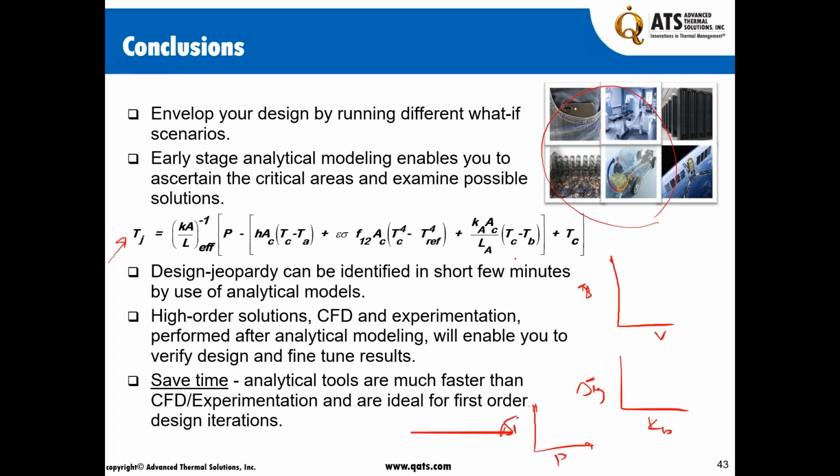It is so powerful to be able to go in there and say, okay, I can change these, and as long as you have a model and really envelope your design, you can say to your circuit designers, this board and this component with the power dissipations you've given me, you cannot put another board of the same power next to it. You've got to locate that in a different location of the system, because the coupling that takes place between the two could adversely impact the thermal performance and the performance of the system.